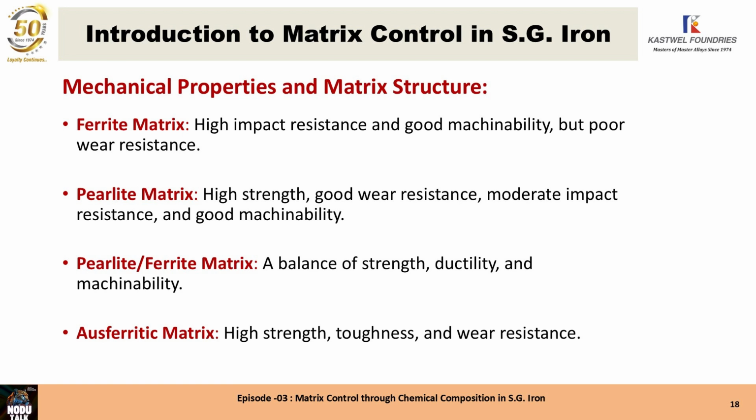Ferritic matrix has high impact resistance and good machinability, but very poor wear resistance. It's a softer, very soft material. So it has high impact resistance, good machinability, but poor wear resistance.